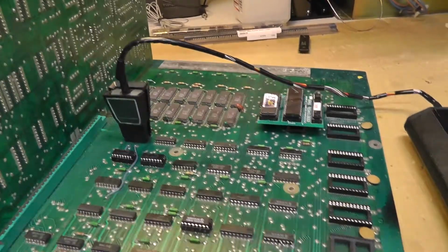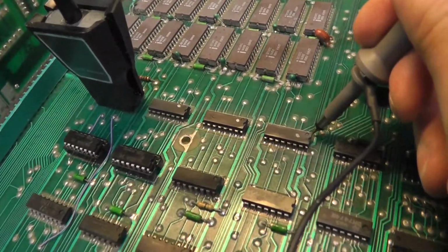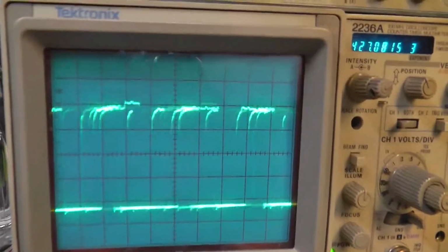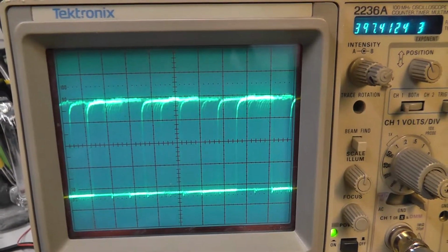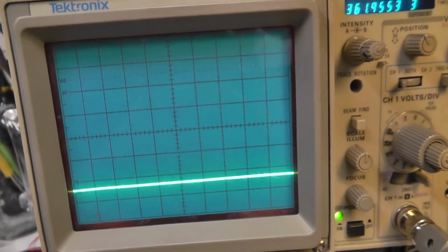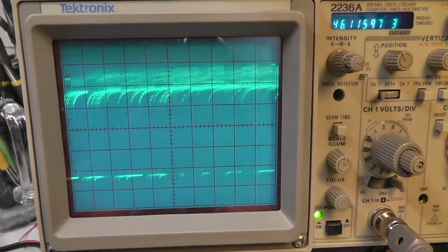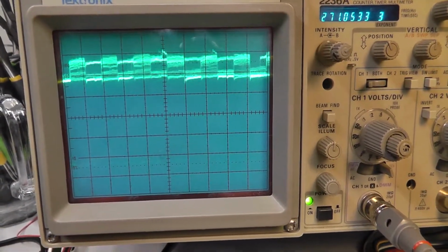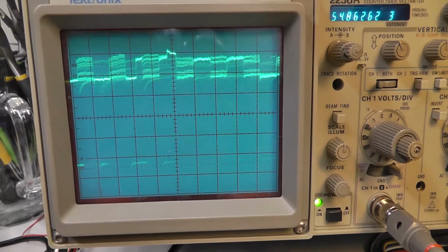Actually, let's power on the scope and look at the signals of all those outputs. We're going to go first chip, pins 1, 2, 3, 4. I'm going to hold it right there. That's 4. We're just running through track mode right now. That's 4. That's 7. These look pretty decent. This is 9. Now, there's definitely some noise on this that looks weird. Look at the tops of that right up there. That looks kind of odd.